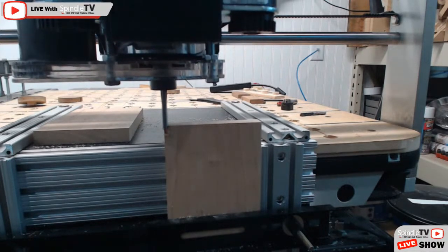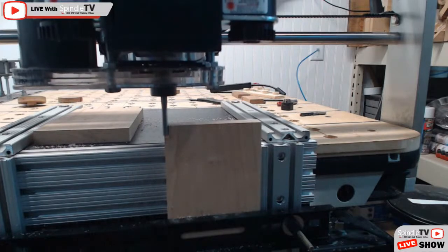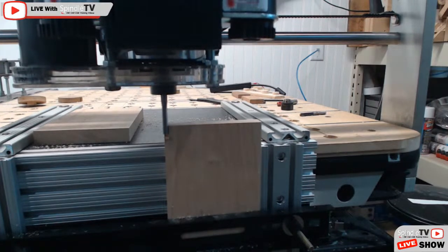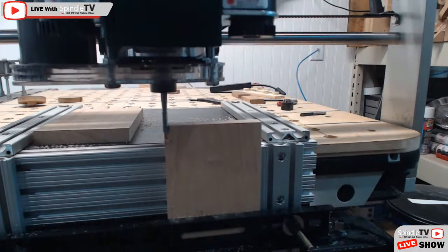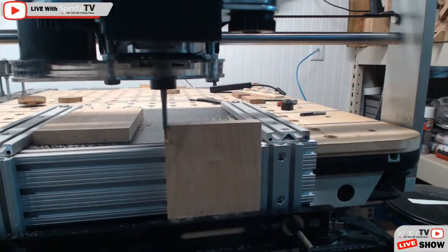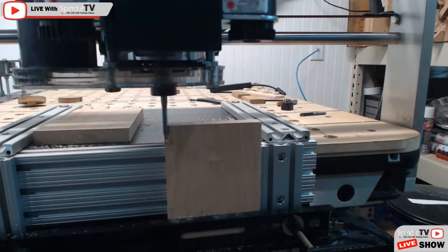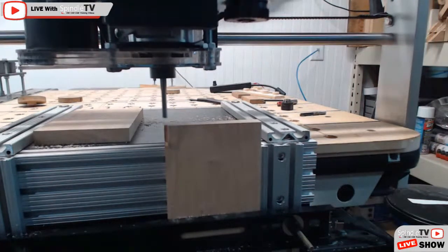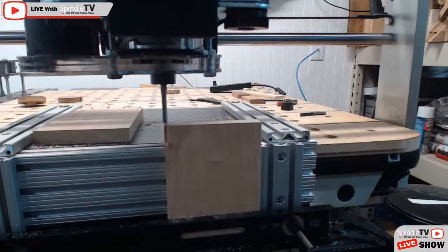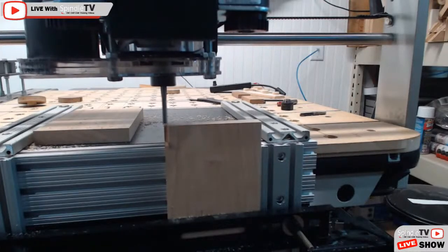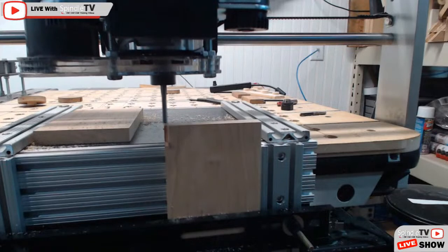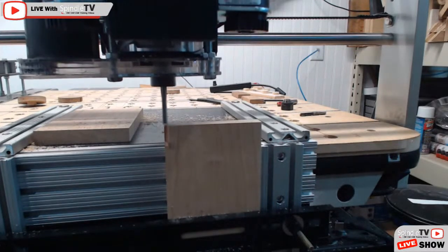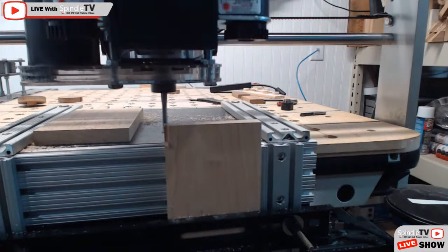I'll try my best to see if you guys can hear me while it's running, but I have it taking 1/8 inch passes for the drill pecking. It's cutting down to 0.6875 inches deep, which is going to be about, I don't know, 5 pecks. And it's going to do that on both ends and then between the fingers of this tailboard.